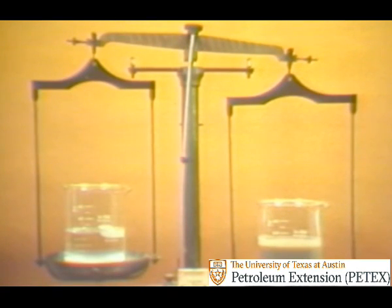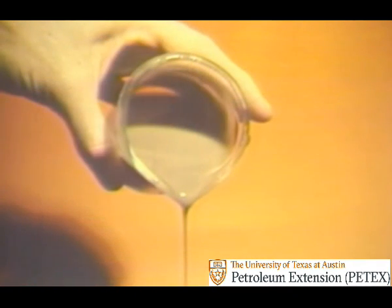Another interesting property of drilling mud is that it is denser or has more weight than water. By just adding clay to the water, we increase the weight. In fact, clay is about 2.5 times as heavy as the same volume of water. Also, viscosity or resistance to flow increases when active clay solids are added to water. The viscous liquid is able to carry cuttings from the hole and support barite.